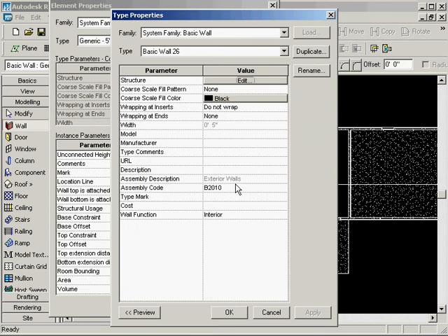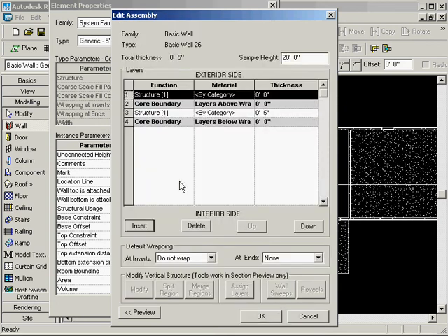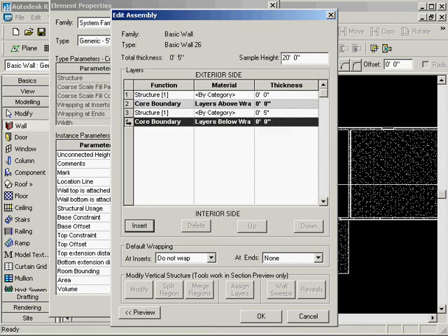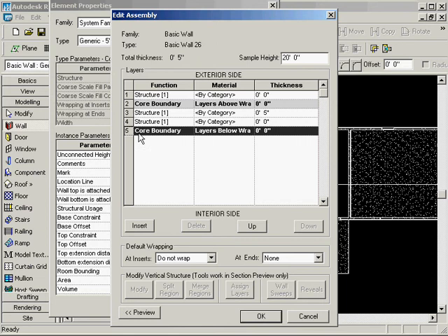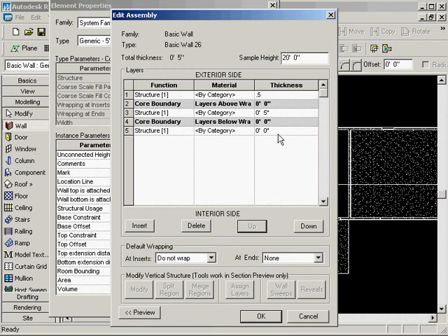but what you'd probably do is create a partition wall, go in here, go into duplicate, give a wall name, and then from there go into structure, and insert a layer of drywall, and maybe go down there and insert another. We'd have to move that one up and move that one up. So we'd have to create a drywall layer here. Might as well do it. And another, 0.5 of an inch and 0.5 of an inch.